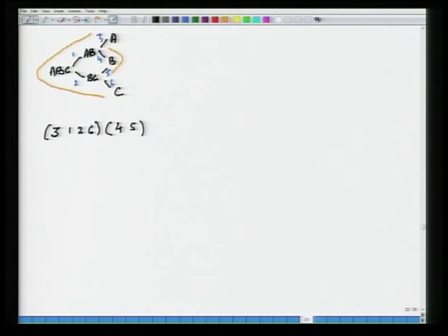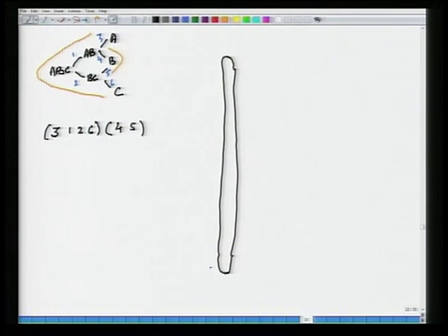let us see. Okay. So, there is a tall column which has got 3, 1, 2 and 6. So, that is the tall column. Let me draw the tall column first. This tall column takes in the fresh feed somewhere in the middle, sort of symmetric. It has got its own condenser and its own reboiler.